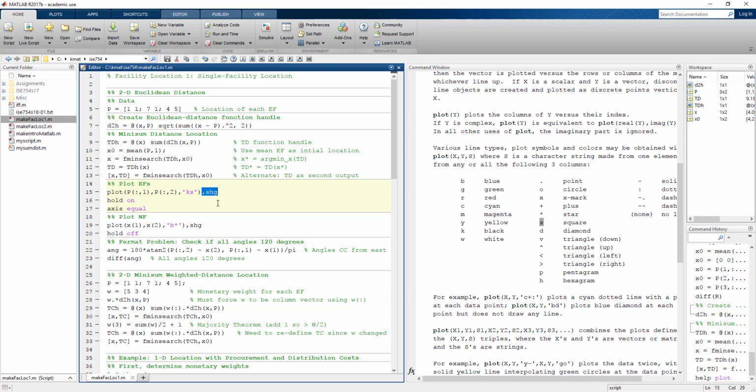But another way you can do it within the script itself is by indicating this command, show figure at the front. So after plotting it, it'll make it a window that appears in front of anything else within MATLAB. And then after I do the plotting, I'm going to execute a command called hold on. And what hold on does is it fixes the plot that I've just done, so that if I issue a second plot command, it puts it on that same plot.